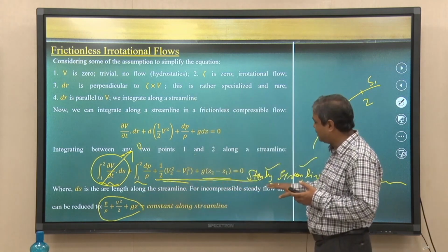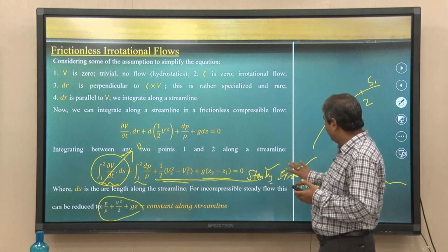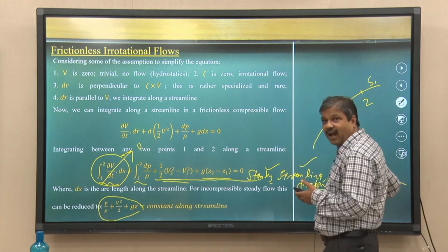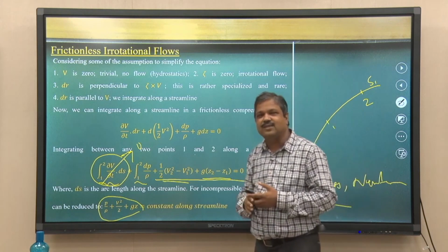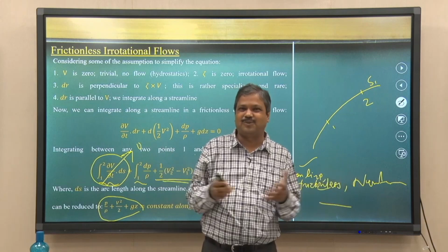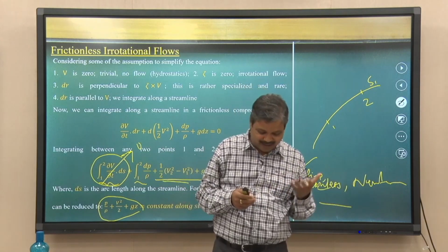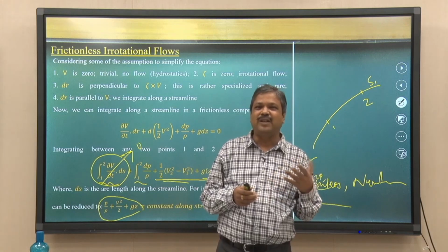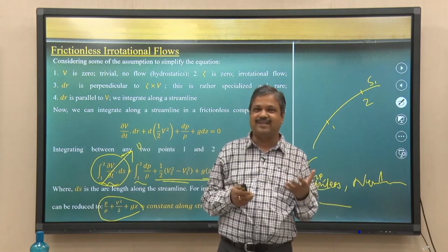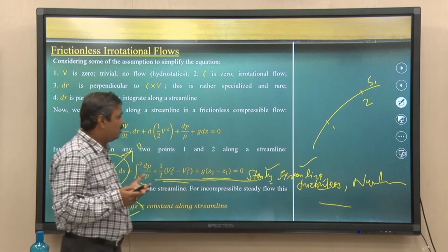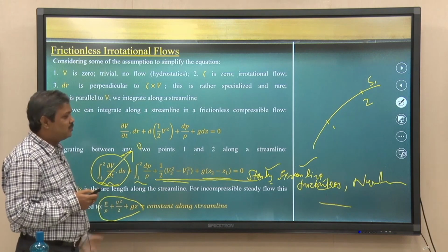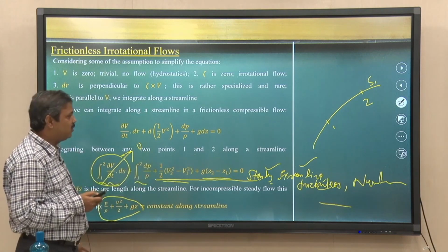Again I am talking about Bernoulli's equation: steady, along the streamlines, frictionless, Newtonian fluid, isothermal conditions, laminar conditions. If you fulfill all these conditions, it is a simple problem that we solve, no doubt. That is the reason we use Bernoulli's equation in many places where these assumptions are not valid. We get the results, we pass the exams, that is not a big issue, but please try to understand it. Fluids are as naughty as we are, so they don't follow these conditions that we define.